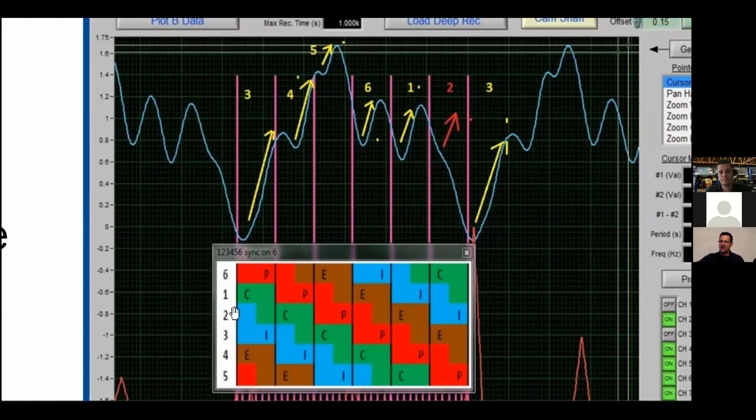So here's cylinder number 2. Cylinder number 2 begins its compression stroke. Let's go back to that relative compression test, that sound we heard with our ears. Forget the amp probe for a moment. What did we hear with our ears? We heard a variation in what? Of load, but what happened to the speed of the crankshaft? The speed of the crankshaft increased as cylinder number 2 completed its compression stroke.